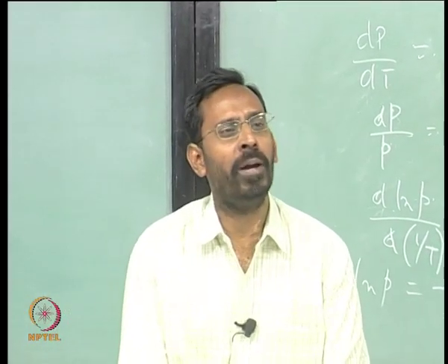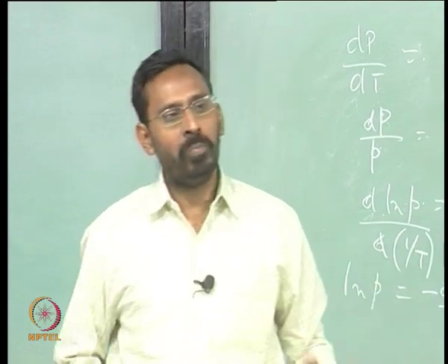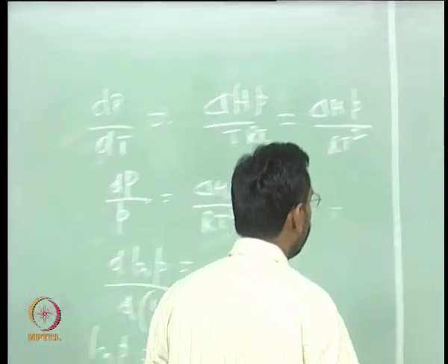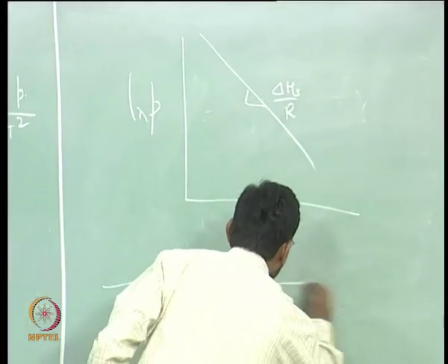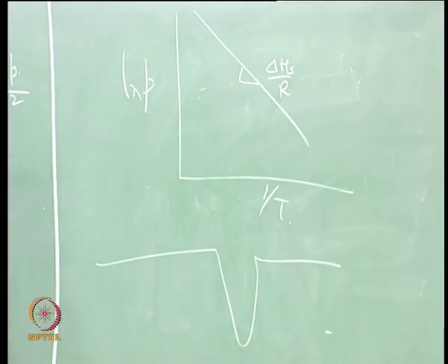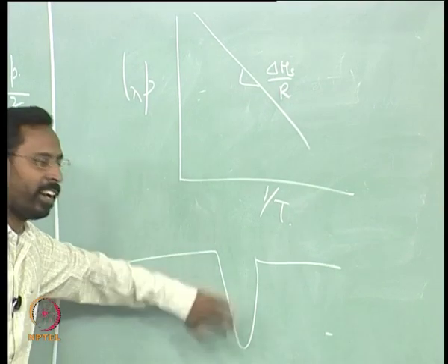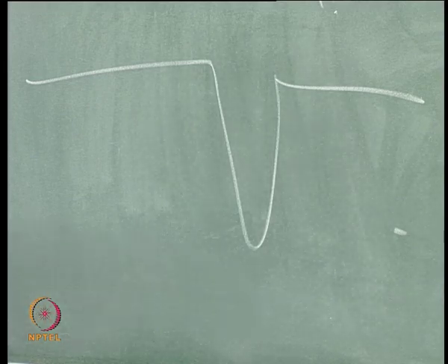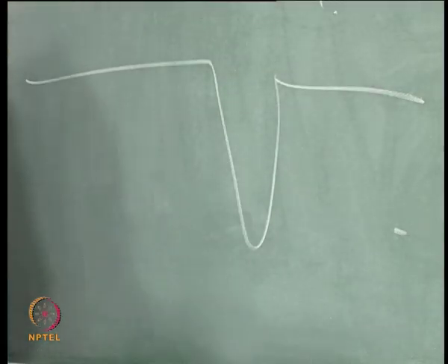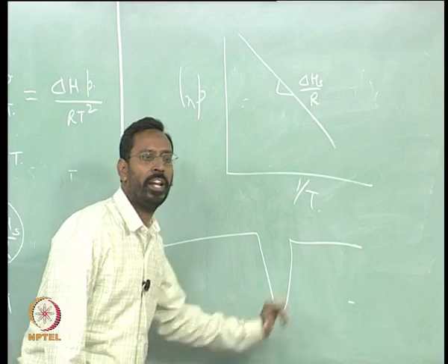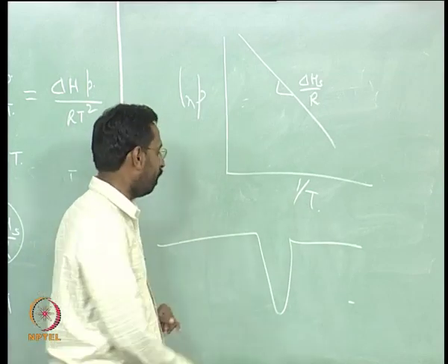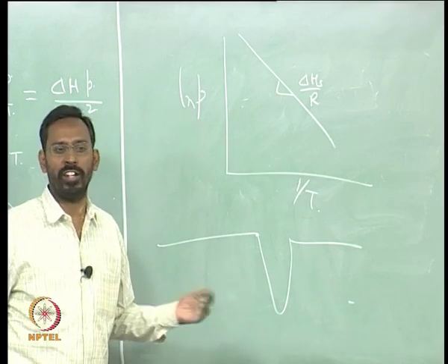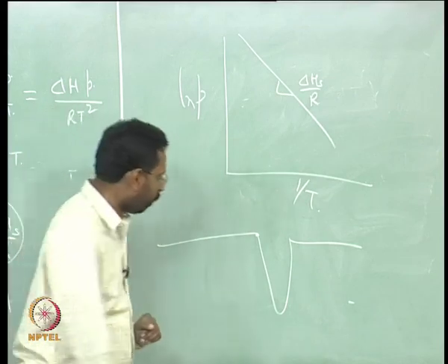So, if the sublimation temperature of the material is below 1500, in principle you would see a strong peak associated with the sublimation. Of course, whether it is this side or that side depends on the polarity that we are talking about. But basically, sublimation being an endothermic reaction, you get an endothermic peak at the sublimation temperature, and this basically represents the onset of the sublimation. And what does this represent?